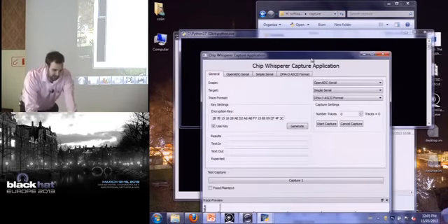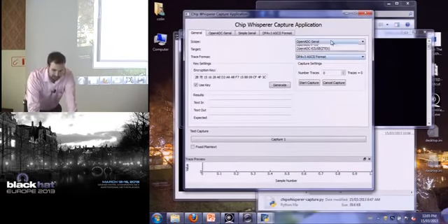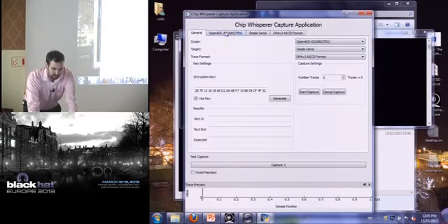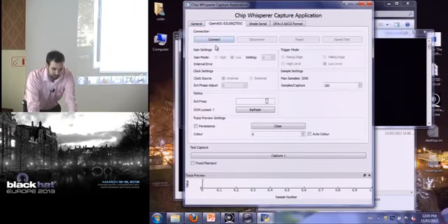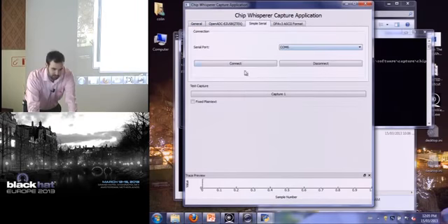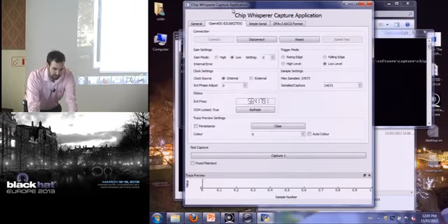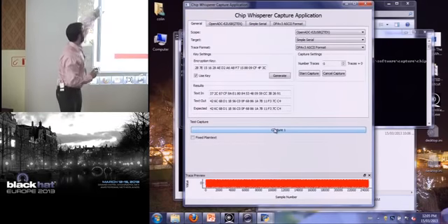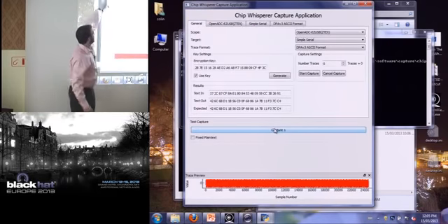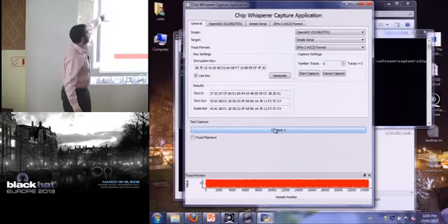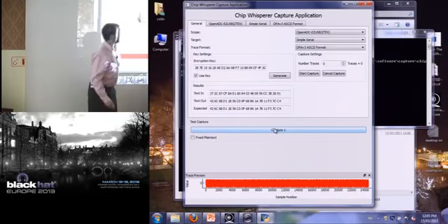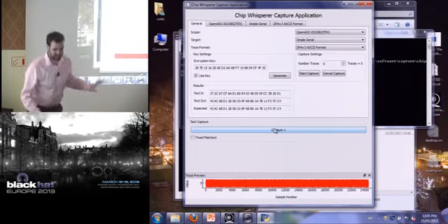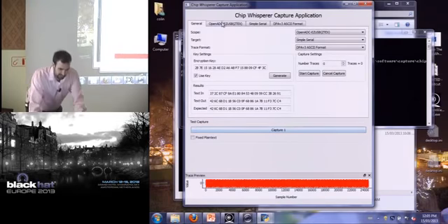So this is the capture application. I select the type of oscilloscope I'm using, and I have this higher speed version connected. And I just connect to my simple serial device. So I can first check that it's working. It just sends it some data, gets the response, and locally this program computes what it would expect the response to be and prints it. It doesn't actually check anything, it just prints it for you to look at.